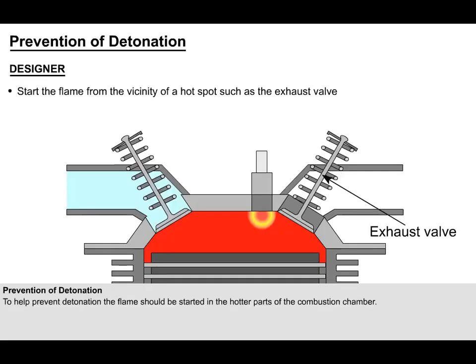Engine designers can help to prevent detonation by ensuring that the flame is started from the vicinity of some hot spot, such as the exhaust valve, so that the end gas is pushed away from the hotter parts of the combustion chamber and compressed into a cooler part.